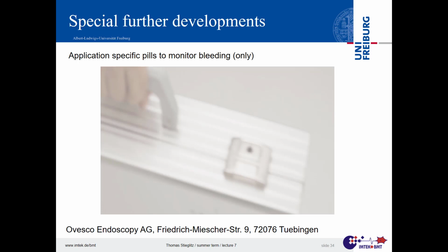I've seen one development that was really a pity. There was a delay of 2 or 3 years where people were nearly ready to go with a foil-like ECG recorder, and it worked perfectly well, but unfortunately they overlooked minimum distances of voltage carrying lines for those applications, and they missed half a centimeter or something like that, and they had to start from scratch to do all the investigations again. If you have that in mind, you browse through, you get a bit of advice from agencies who are good in that, and then you can do it in a, let's say, 10 years time frame. It doesn't go faster. That's the downside.